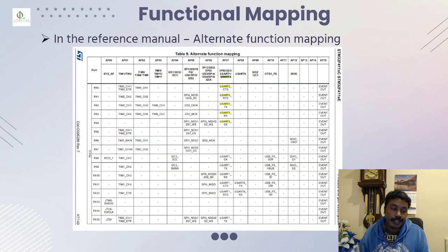And then we were just learning about alternate function, how one same pin can be used for different functionality, and how it can be mapped when you want to communicate with the alternate function to the microcontroller. We're learning about port A2 because we're going to use this as a USART2 transmit pin. And if you link in this table PA2 and USART2 transmit, it's using AF07, alternate function 07.